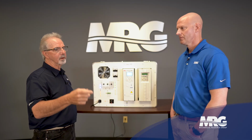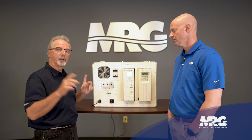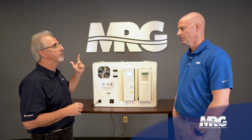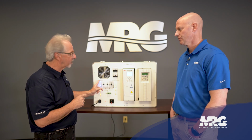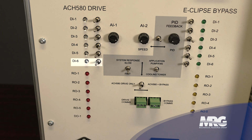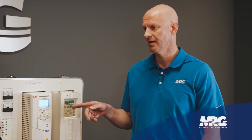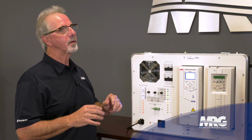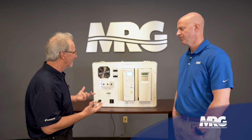When I get the event input from the fire department, they'll give me a contact closure and I'll get a run permissive. That means they have opened the smoke damper and now they're giving me a run permissive. Now they're going to send me the run command. This is my run permissive here. If I lose my run permissive, the system will shut off. That call is going to come from the fire system, not the building automation system. Building automation has to be considered as if it caught on fire and melted down. It no longer exists. I just want to make that really clear.